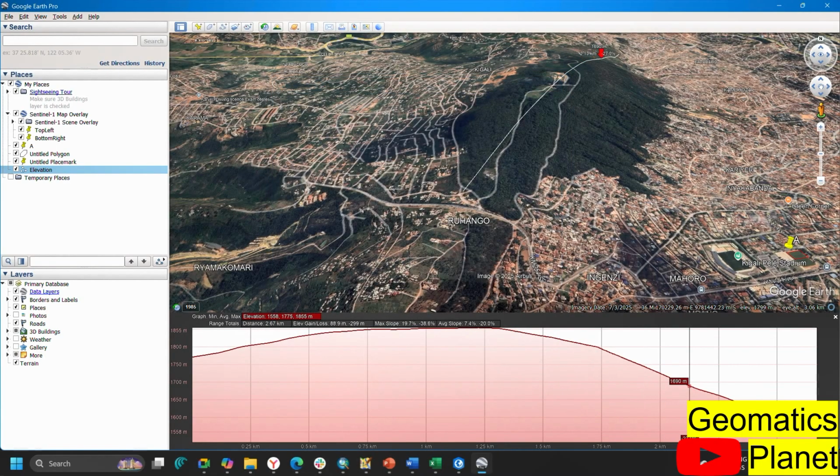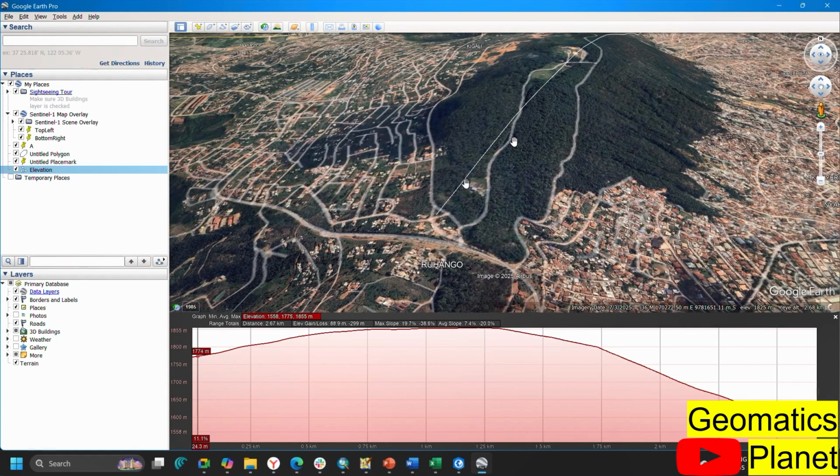Once you do that, you will see that these have changed to kilometers, the elevation here has changed to meters, and these have changed to the UTM coordinate system, as you can see here. Then you see that this is showing you in meters. So from here, the beginning, look at where the arrow is showing up here in Mount Kigali. From the beginning down, following like this, you can see the percentage of elevation, the distance along that line from what I measured, and the minimum and maximum slope. As you can see here, this is how it goes, and this is how flat this place is.